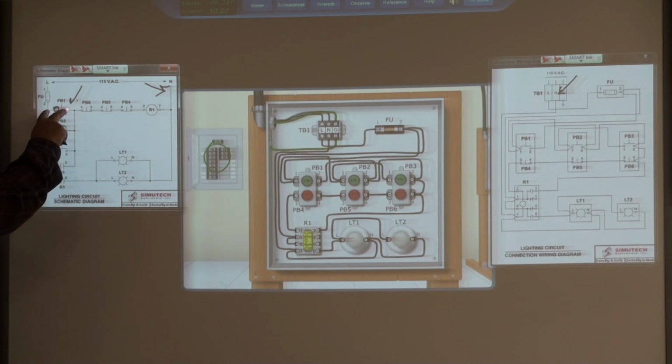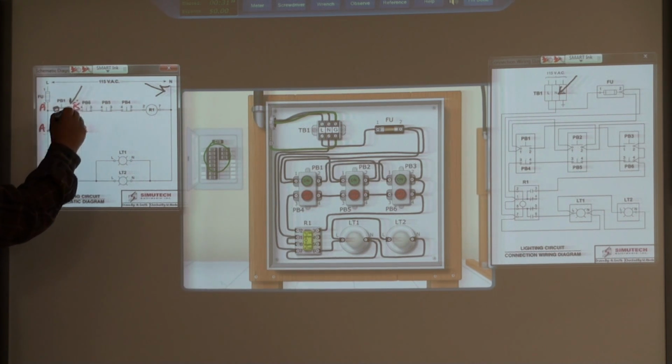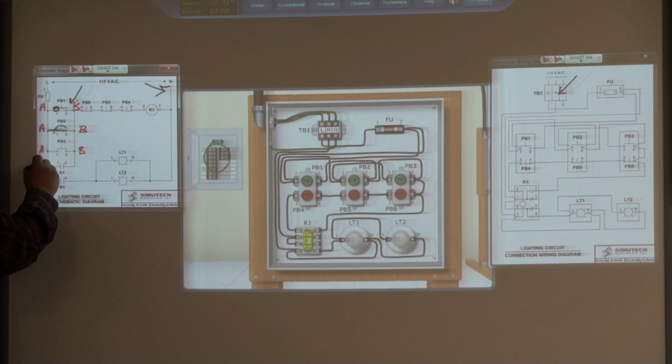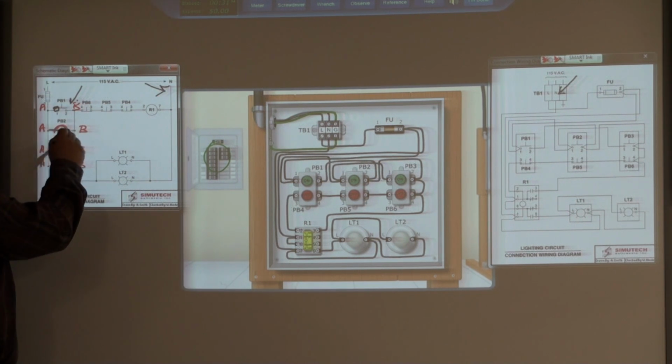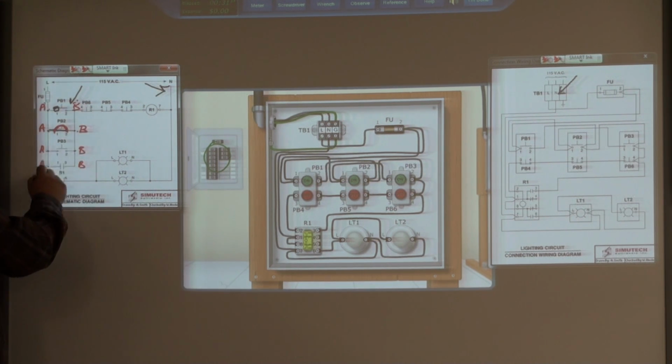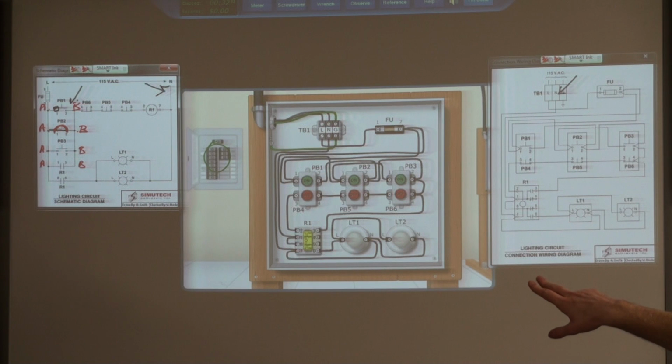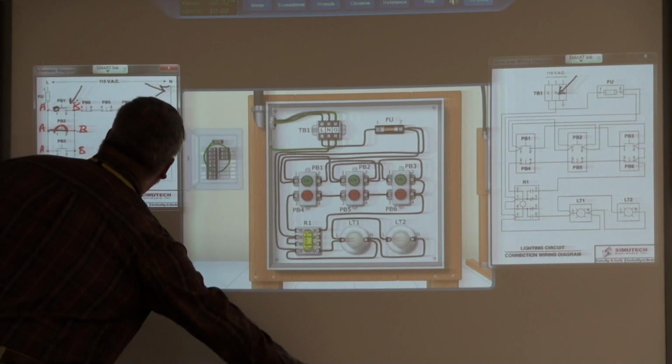Well, you would get a zero potential across all of them, because they are at the same potential. So let's call this A and this B. Under normal off conditions, A is not connected to pin B until we press the button, right? But this one is shorted, so A becomes automatically connected to pin B. So whatever I'm measuring here to here, I'm also measuring here to here. If they're all supposed to be off and the circuit's de-energized, and you're still reading across, you couldn't tell it at all. Very good.